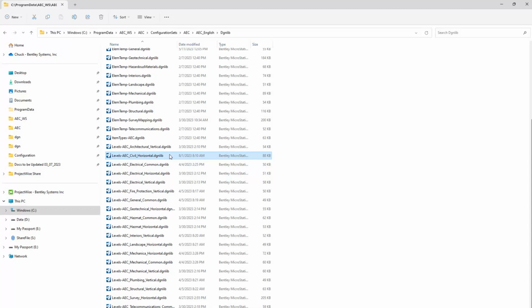Workspaces allow organizations to centralize CAD standards on a server, or essentially to have a single source of truth. For example, you wouldn't want someone to draw an edge of pavement on a heavy line weight and a color of blue and have another person draw an edge of pavement on a lighter line weight and a color of red. It would be difficult to distinguish a pattern of standards, a common appearance, to those particular drawings. And so standards are essentially what a workspace does: it creates those standards and makes those easily accessible for the user.